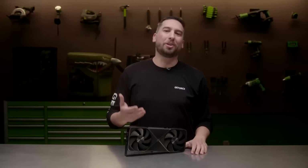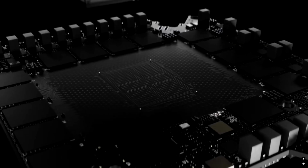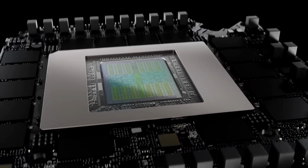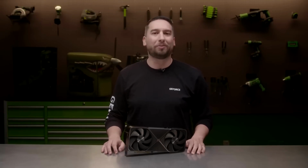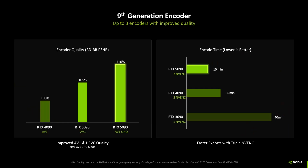Now let's take a closer look at our newest flagship graphics card, the GeForce RTX 5090 Founders Edition, which is also the fastest dual slot card in the world. The RTX 5090 has 32 gigabytes of ultra-fast GDDR7 memory running at 28 gigabits per second. It supports PCI Express 5.0, which has a maximum bandwidth of 32 gigatransfers a second, double that of PCI Express 4.0. The GeForce RTX 5090 is equipped with 3 9th generation video encoders and 2 6th generation decoders for significantly faster video exports and enhanced live streaming.